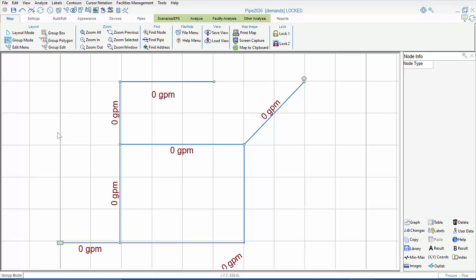We recently discussed demand type, and as you would expect, residential meters always have a demand type of 0 or R for residential demands. One important consideration is that while residential meters are assigned to a pipe, the flow is calculated at junction nodes since the software does not have a routine to draw flow into or out of the system directly from a pipe.